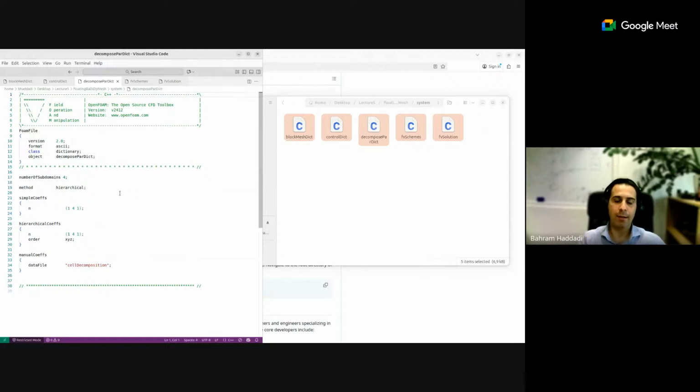If you have a serial compilation, the DEM will run in serial. If you have OpenMP, then it will run with OpenMP on the CPU. And if you have a CUDA compilation, it will run in parallel on your GPU card. So depending on what you have on the other side, it is like that. But on the CFD side, it's either serial or MPI. These are the 2 options available at the moment.